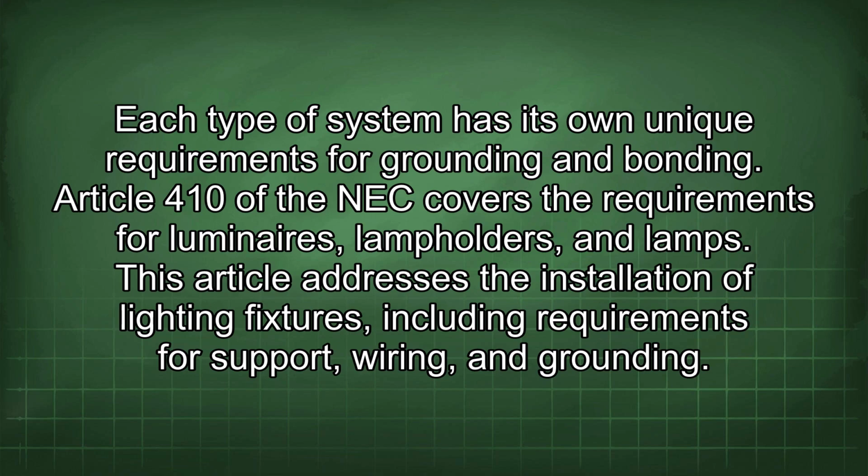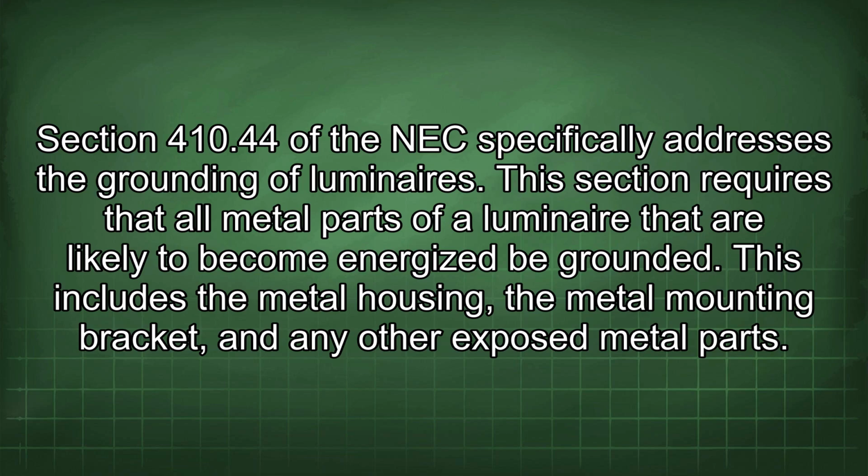Article 410 of the NEC covers the requirements for luminaires, lamp holders, and lamps. This article addresses the installation of lighting fixtures, including requirements for support, wiring, and grounding. Section 410.44 of the NEC specifically addresses the grounding of luminaires.